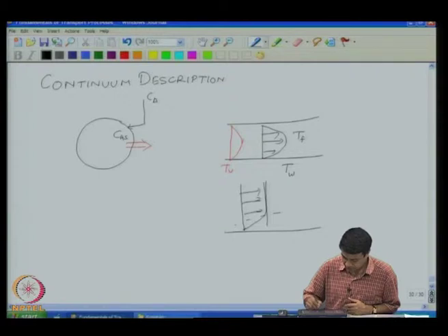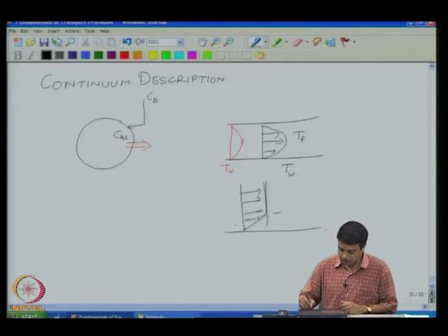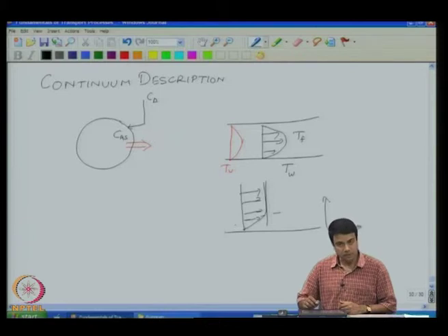And we will try to find out the dependence of the temperature with height away from the surface, as well as how it varies along the plate. And of course, the flux can be determined from the variation of temperature near the surface using Fourier's law for heat conduction.